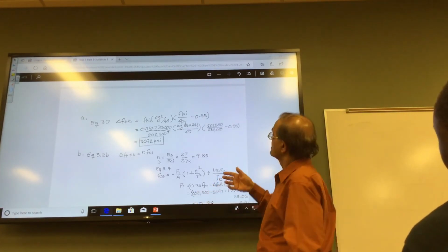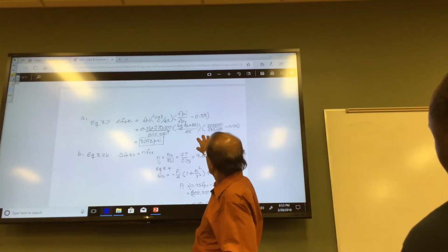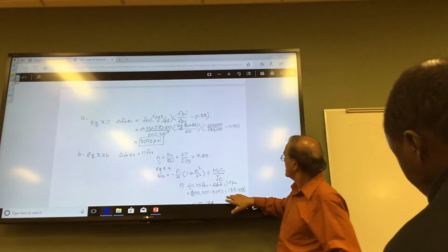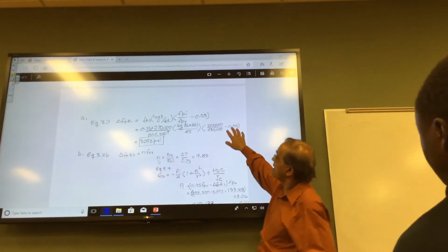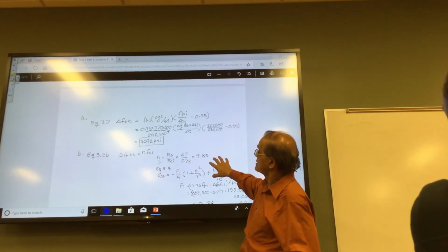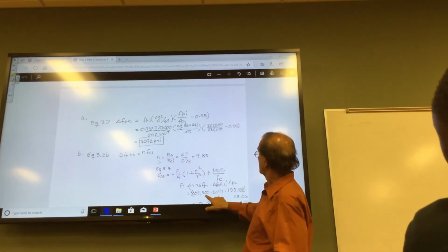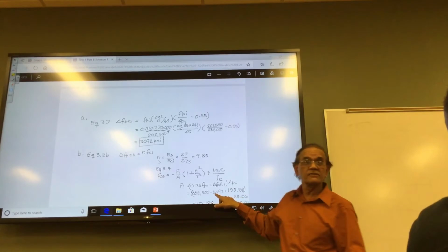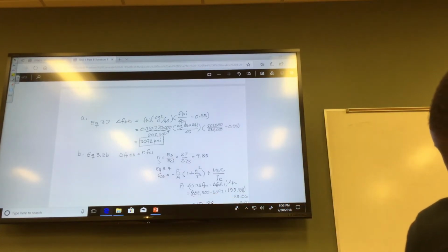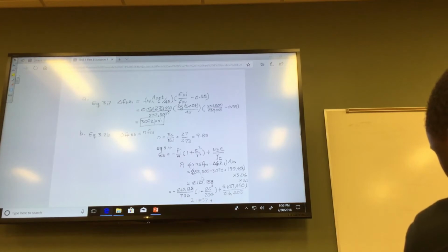For example, because the relaxation happens before the elastic shortening, I simply took the 3 ksi out for 5 days. So your PI is now 202.5 ksi minus the 3 ksi we got for relaxation for 5 days.